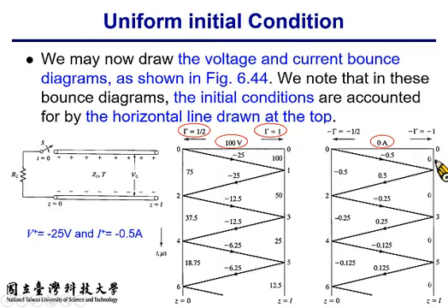So here we have a reflected signal of minus 12.5, that is minus 25 times 1/2. And at 3 microseconds it reaches the right end, and it gets reflected totally because the reflection coefficient is 1. So the minus 12.5 signal reaches the left end again at 4 microseconds. And this time the signal size is diminished by half again, as minus 6.25, and gets reflected again. As you can observe, the signal becomes smaller and smaller, which means more and more energy is dumped into the resistor to the left.